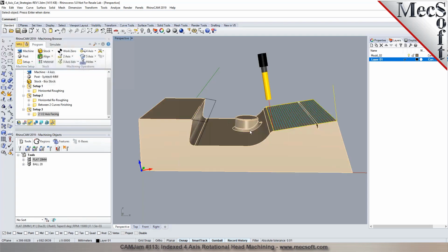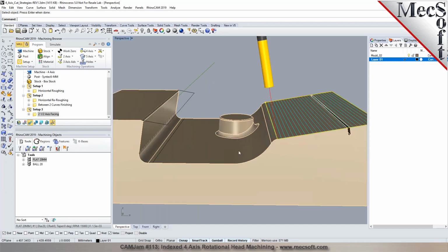And now we can apply a similar toolpath in here for finishing these sections in here as well, right? Yes. You want to flow along this. So again, if you want to do this, I'd normally go over with the same cutter you've got there, the flat mill, and then go over the ball afterwards. I'll just leave a little bit extra on there, say 0.6.